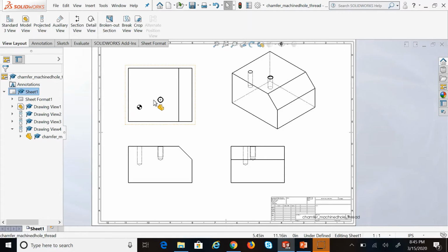In a drafting, if you remember from the past, we never add any extra detail to the isometric view. So in isometric, you should never ever show hidden lines, symmetry lines, dimensions, or anything. Isometric is just for visualization. You should not put any information on it because it's ideally a redundant view.